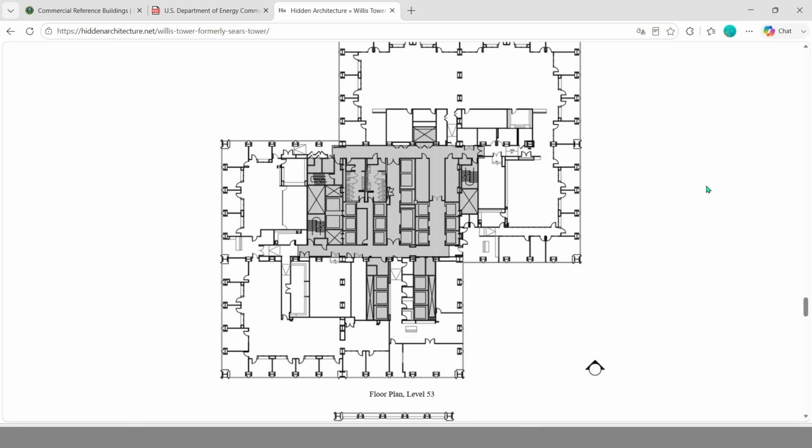If you already have floor plans, your zone model should follow the space used and the orientation of your floor plan. For example, in this floor plan, you can combine the south side offices as one zone, the open office area as one zone, the conference room as one separate zone, the core as one zone, and so on.